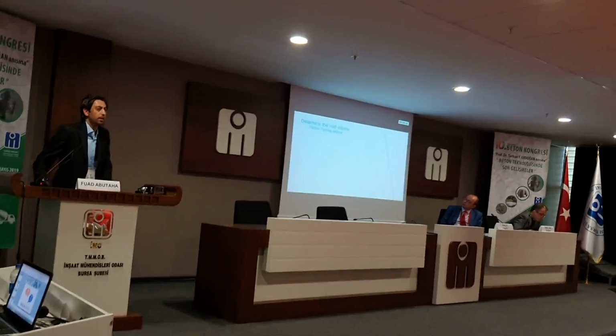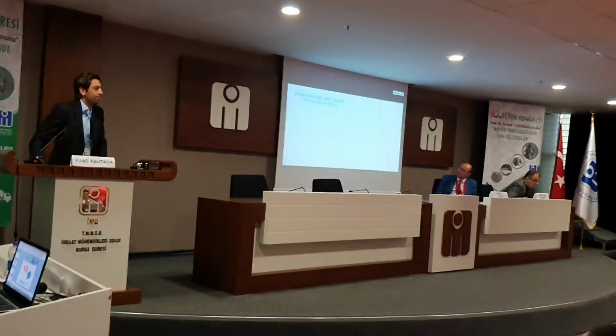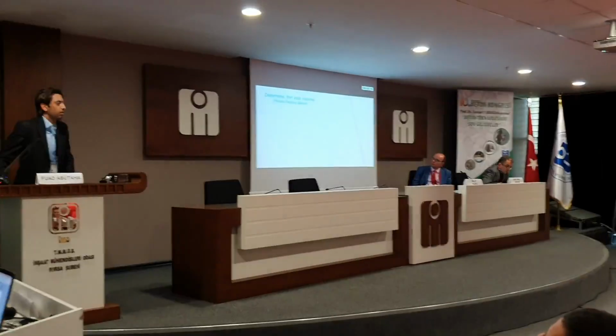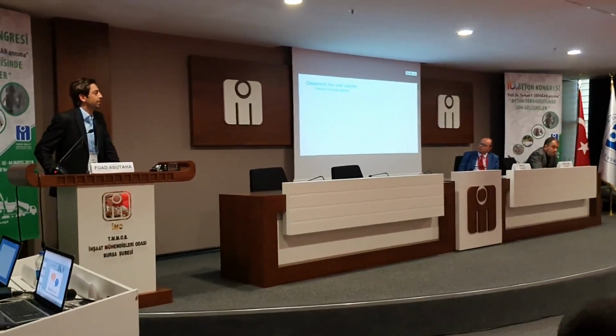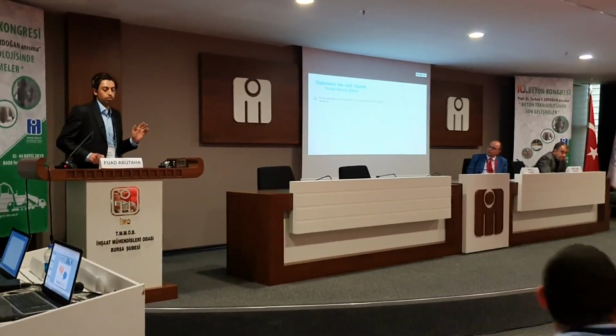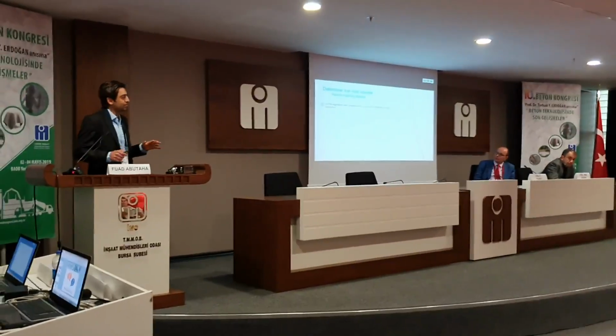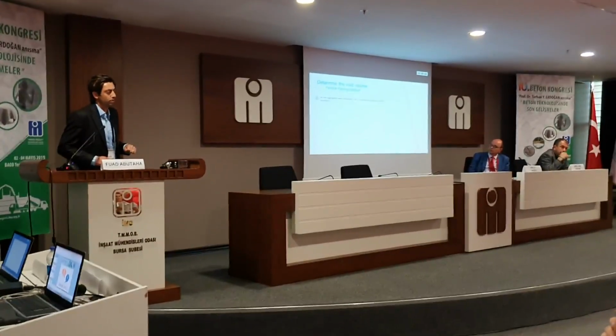To determine how much volume we have for each replacement level of the coarse aggregate, we use the particle packing method. The steps are as follows: first, all the aggregates were prepared in a saturated surface dry condition.